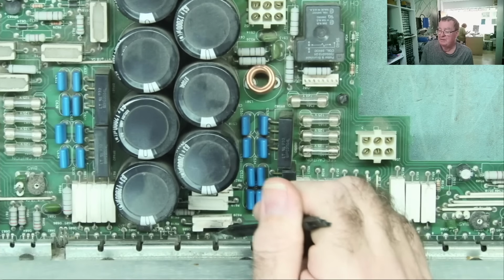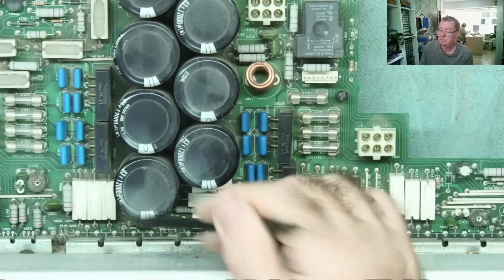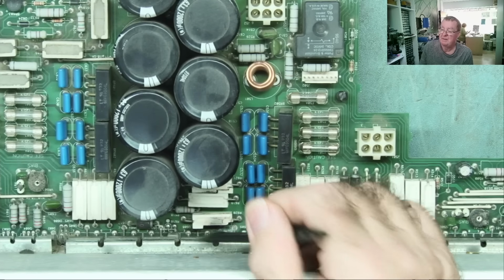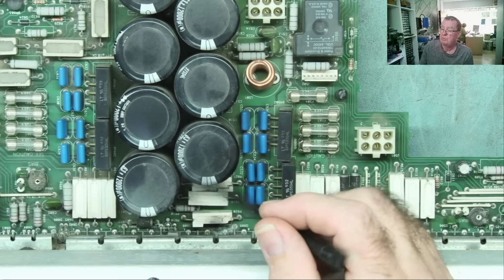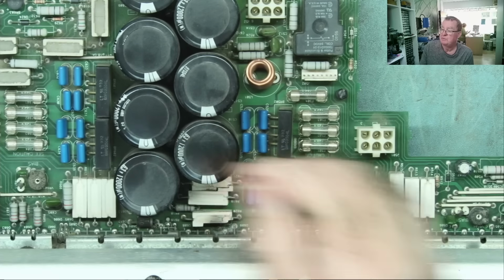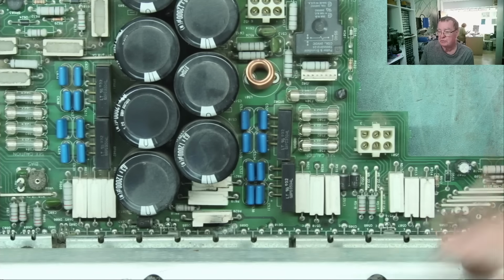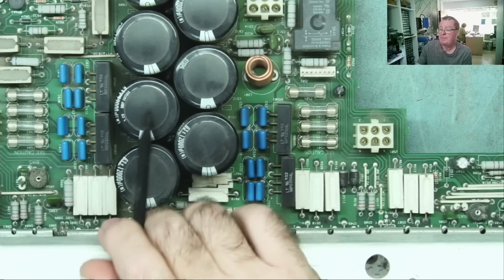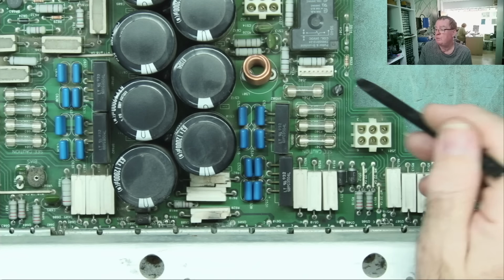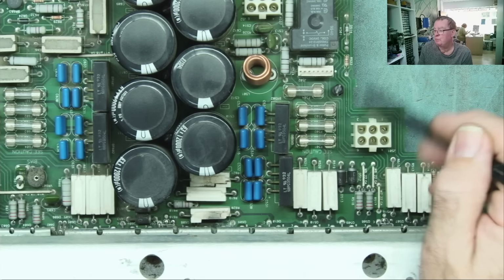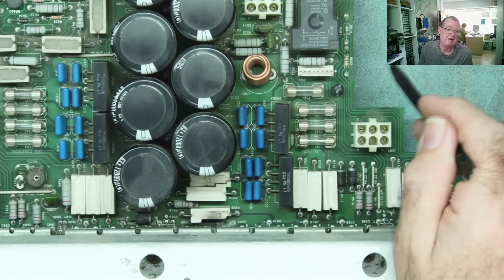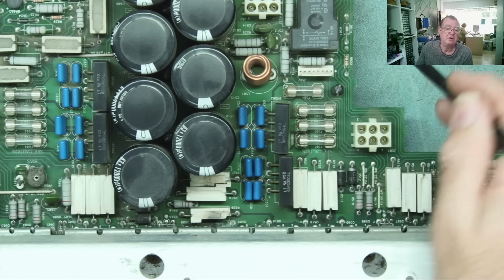So in the example of this, I have short circuit transistor or MOSFETs here. Then the power will come via the bridge rectifiers. We see some here, some here. So if these are short, they could be short. That power to them will come through fuses, for example, which we're going to talk about in a moment. Maybe also you'll find thermistors back in the circuit.